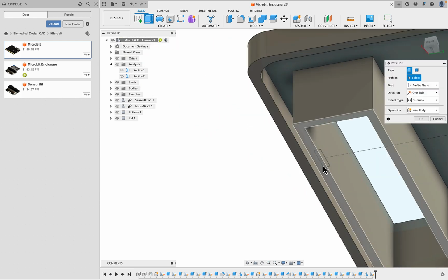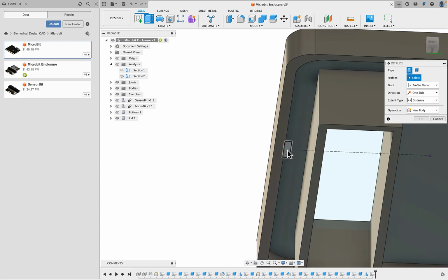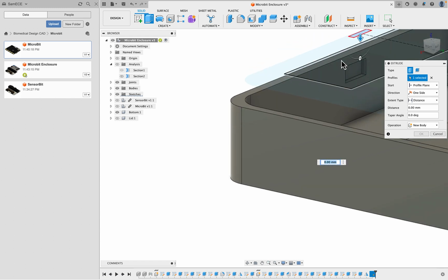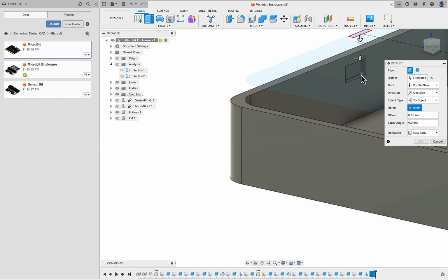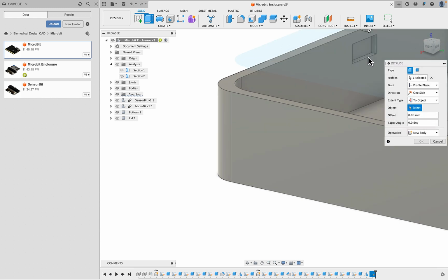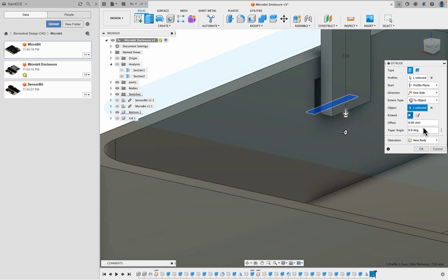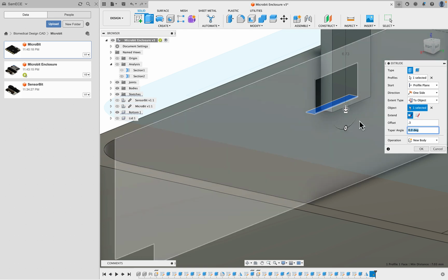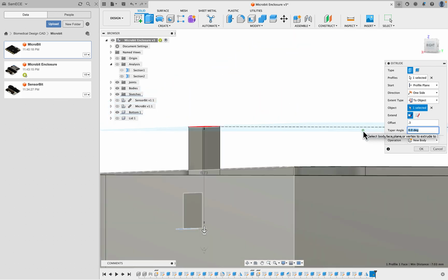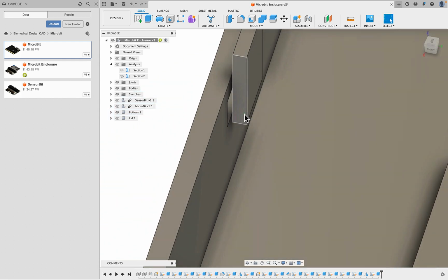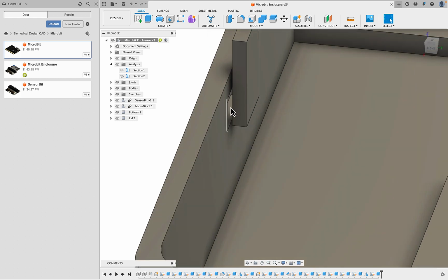And do the extrusion of this one to the bottom of this one. There we go. I did a 0.3 offset last time. It's not really necessary because again we do a triangle just a little bit, but just to be consistent I'll do it again. So now we can actually disregard that offset because now there are 0.3 millimeters between the sides.